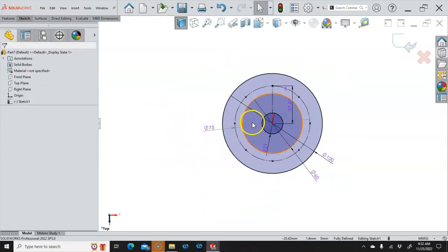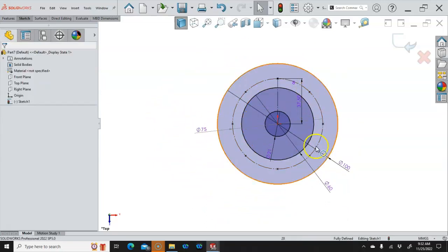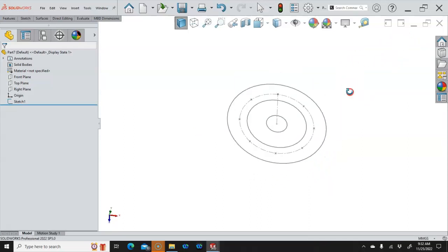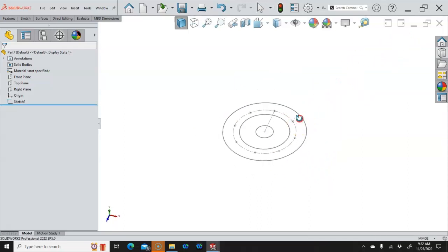All right, so where last time when I copied the sketch, I did lose a couple of relations, and again that varies when I copy the sketch as opposed to the sketch geometry. I get pretty much everything in place. All right, so when we go, well, pretty much going to be the same thing except for the 13 millimeters.